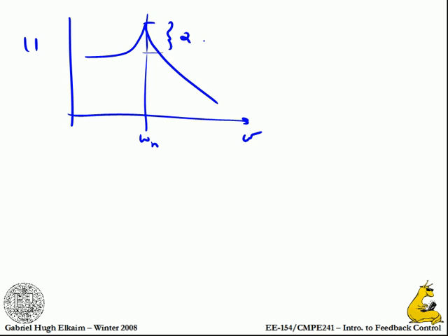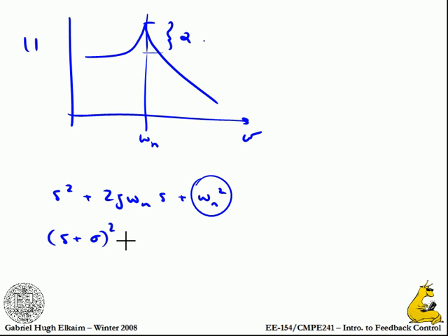The reason we use this, by the way, is because we can write the transfer function as s squared plus 2 zeta omega n s plus omega n squared. It's a very convenient form to carry around, and of course, that term is very obvious. Whereas omega d is slightly more complicated to pick out, because to write it with omega d, I've got s plus sigma squared plus, what, omega d squared? Is that right? So I've got to write it like this, which is a slightly more complicated form. So there are sort of historical reasons we carry that around.